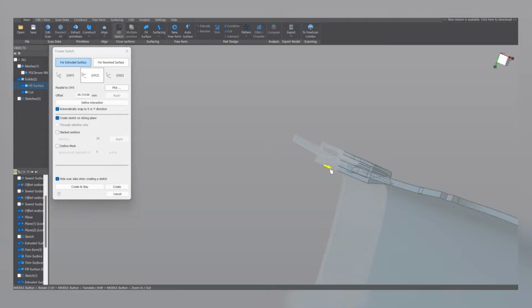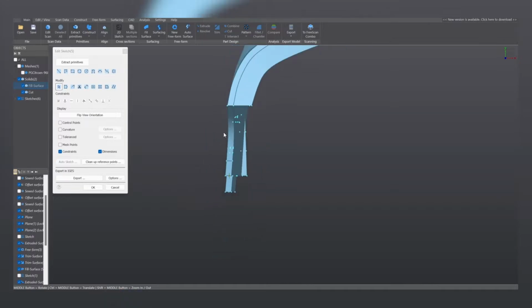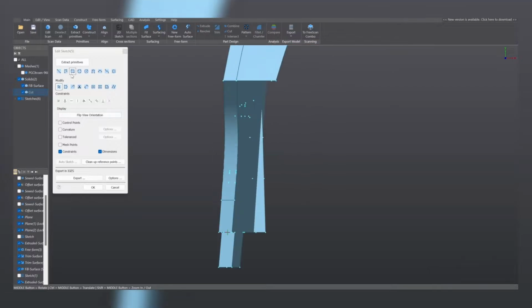Let's try with a plane on this position. Okay, let's now draw a rectangle. Actually, let's display first of all the previous sketches that we used. There we go. And what we are going to do, using these sketches as reference, we are going to design this rectangle over here, making sure that we cut enough material from the other solid. Click on OK.